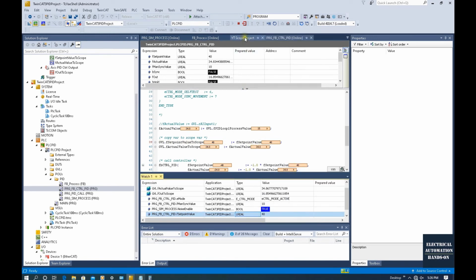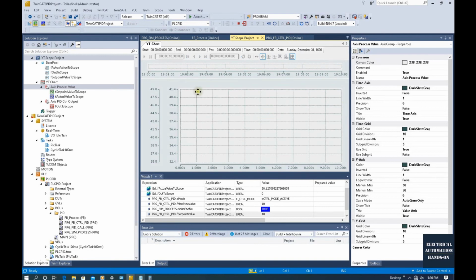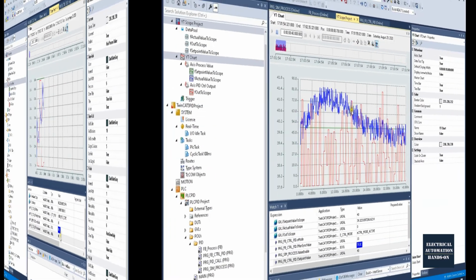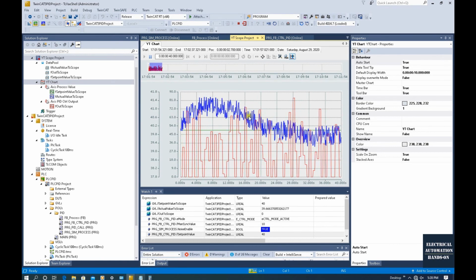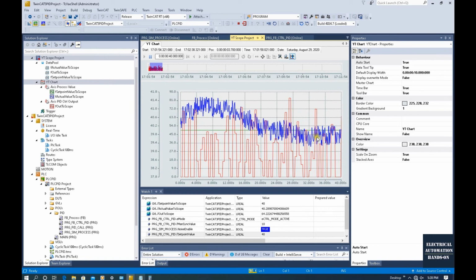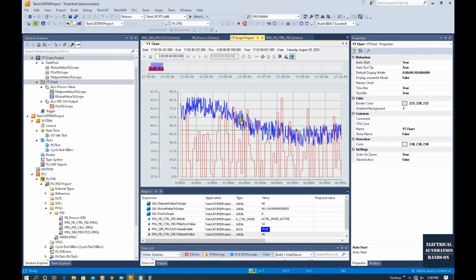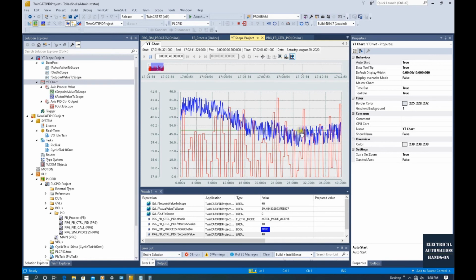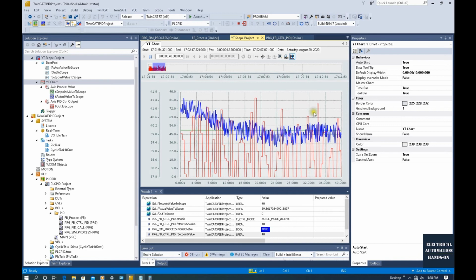If we shift back to the scope, click this start record. So from this curve, we have a rough idea how that PID works. So now this process value is working around this green set point, but we have overshoot a little bit. Also because this process has a noise, so this output control is oscillating here.